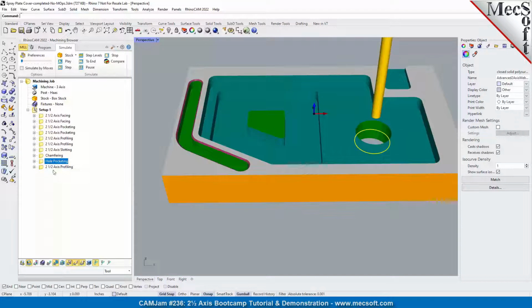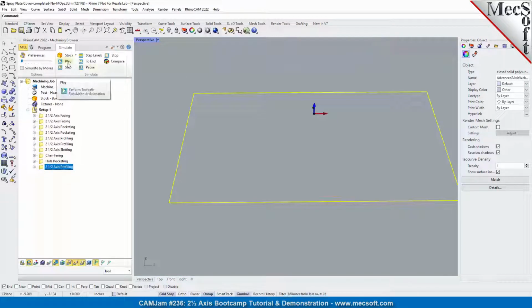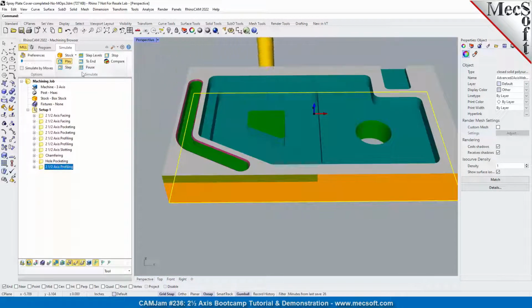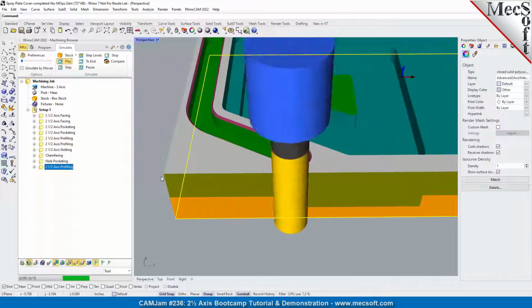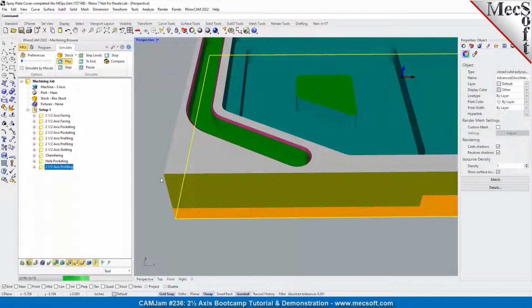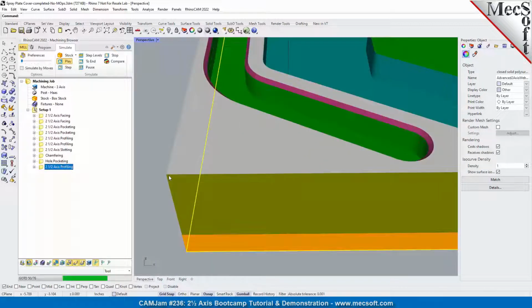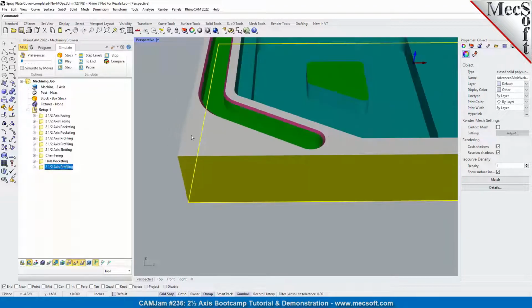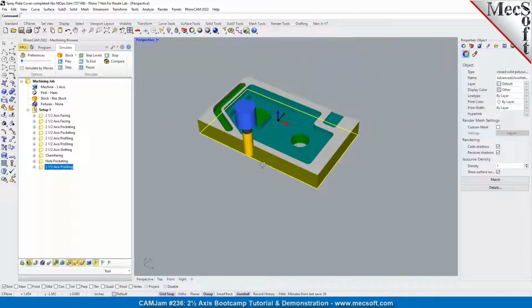So there's our through hole and profiling. Nice square corners. That's really important to use that. That's a very good enhancement we recently added. If you're cutting any type of cutouts that you want a square corner, you don't want that tool to roll around it because it will degrade that corner. So using the sharp option on the profiling, it goes right past the edge before it changes direction.